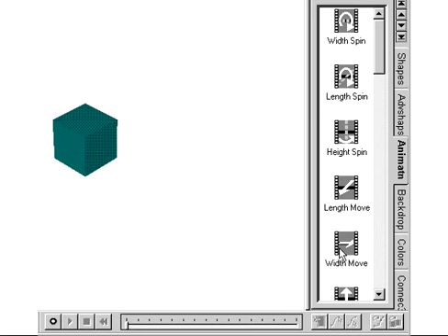To animate your model, drag an item from the animation catalog and drop it on the model. Click the On tool on the Smart Motions toolbar, then click the Play tool to begin the animation.